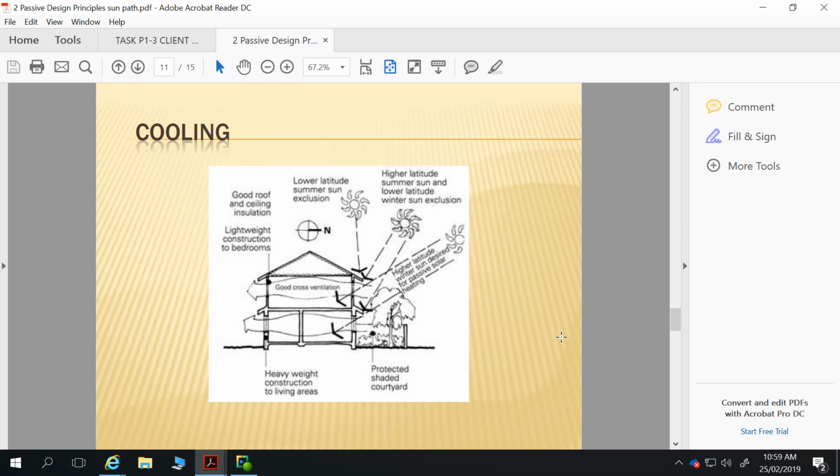Yeah, we have to meet a 6-star energy rating. Now that's if we go for a separate assessment. There, you can work through the deemed to satisfy approach in the NCC to say we do this to meet those requirements, but basically pretty much everybody goes through getting an energy assessment done to meet those 6 stars to save on all the installation costs and so on. So for that matter, yeah, you've got to meet those 6 stars. You won't meet those 6 stars if you have a very poorly oriented house with no shading and things like that.